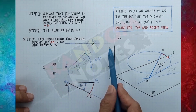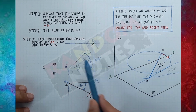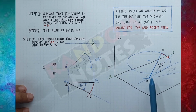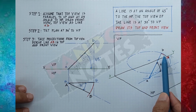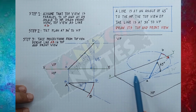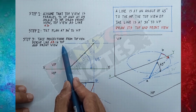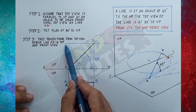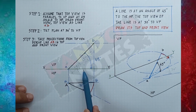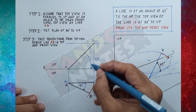This projection from B is this circle or this path which this circle is taking, which means anchoring my line at this point, if I rotate it at 45 degrees with this point as center, the path which this circle has taken is this line. If point B is on this line, that means it will always remain at 45 degrees to the horizontal plane. Now I'll take another projection.